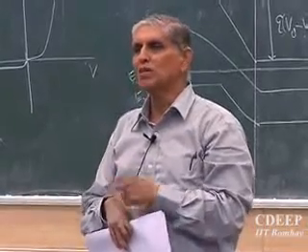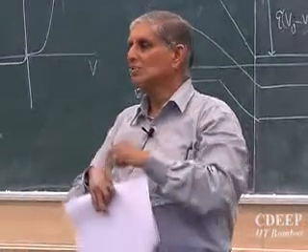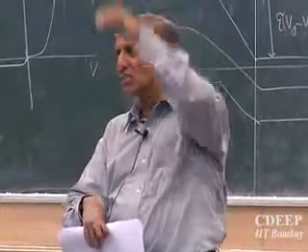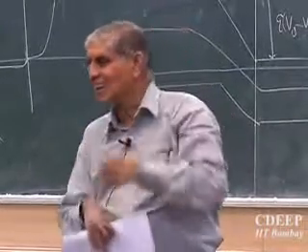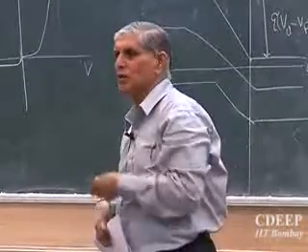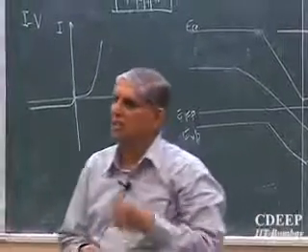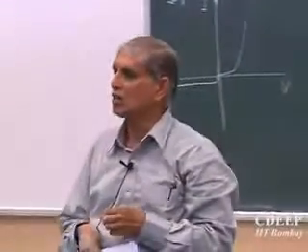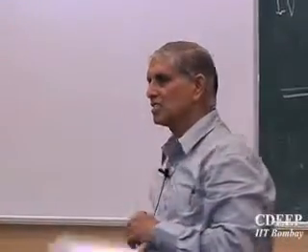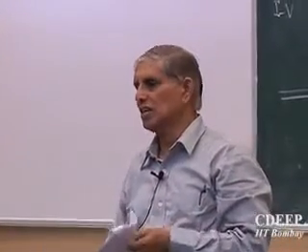If I apply reverse bias, what will happen? This barrier will further increase. So it is unlikely that carriers will climb. The probability of climbing is much smaller. A very small current, which existed anyway, continues to flow, almost negligible. This characteristic comes from bands. We'll see next time, band bending for the bias.